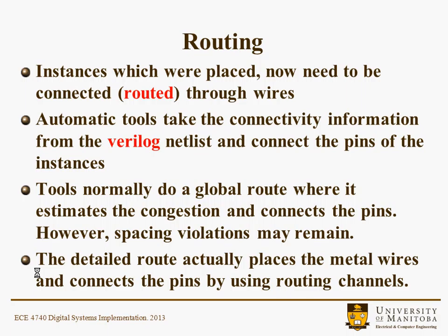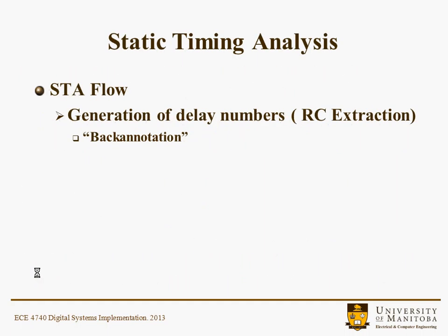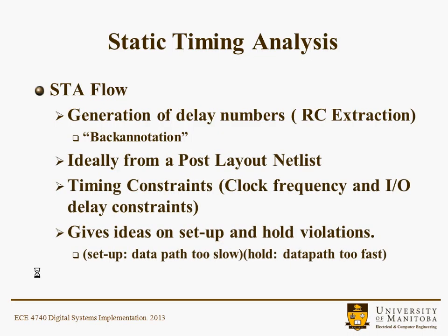Static timing analysis, we'll spend some time looking at basically generation of delay numbers, and that's like RC extraction. The terminology that you might hear is back annotation. Back annotation means once you've got a layout, you back annotate, you bring in the parasitics onto your netlist, and then you can simulate your circuit with the parasitics included. Typically they're going to be capacitances. So it's ideally done from a post-layout netlist, and it allows you to see if you're meeting your timing constraints. It gives you some ideas on setup and hold violations.